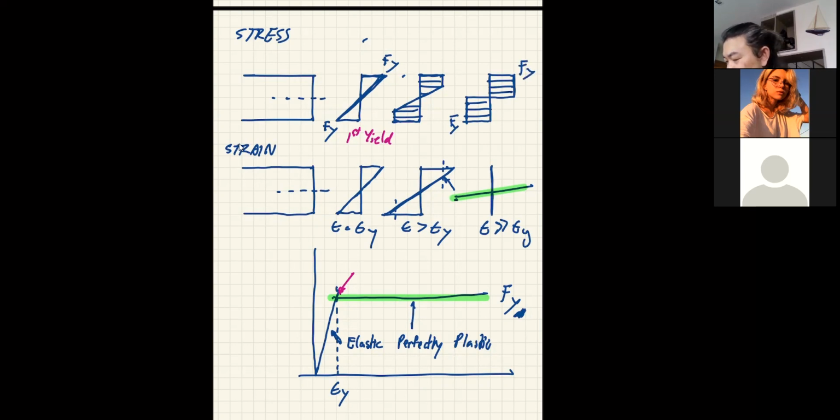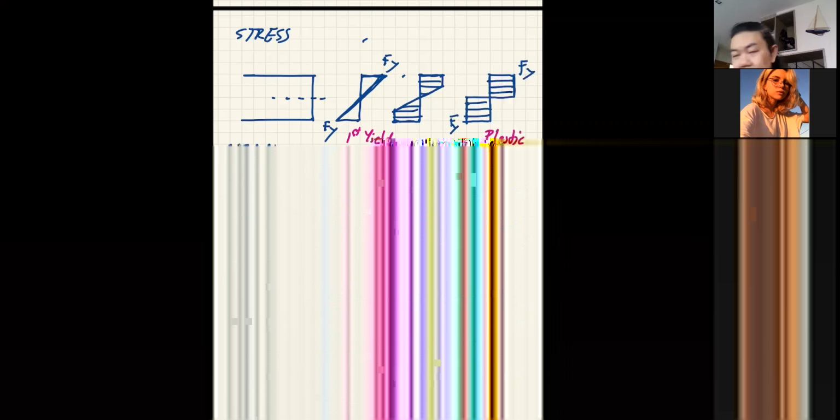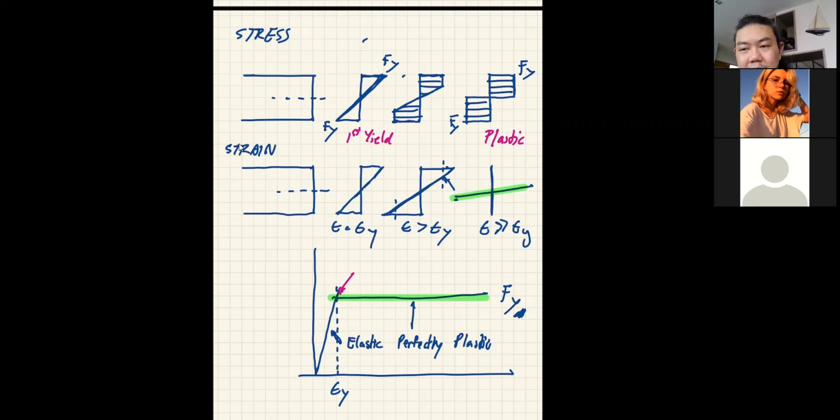Okay, so this is a plastic. And when the entire section yields, at that particular location, it will form a hinge. So when you load your structure until another hinge is formed where the maximum moment occurs, that is when your structure is really going to go. Okay, and this is what we can reach in steel structure.